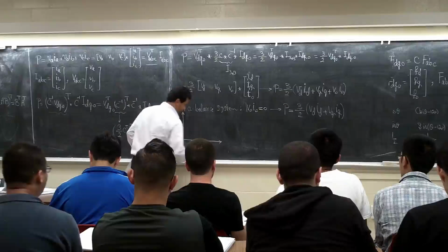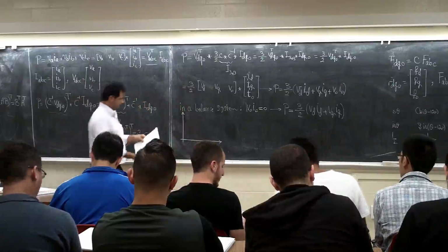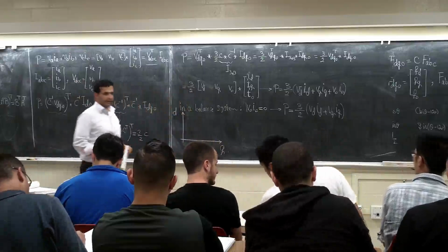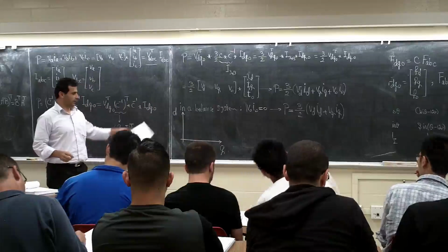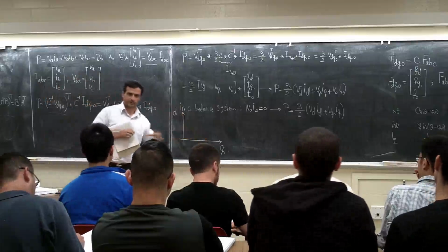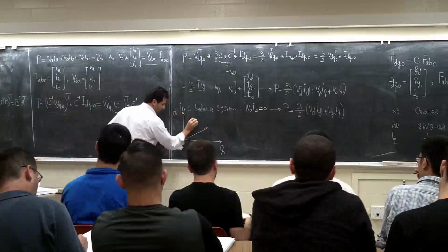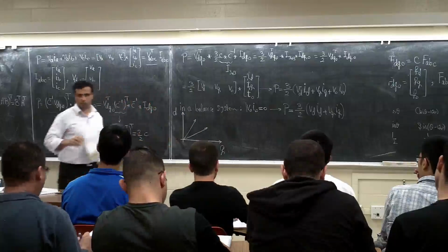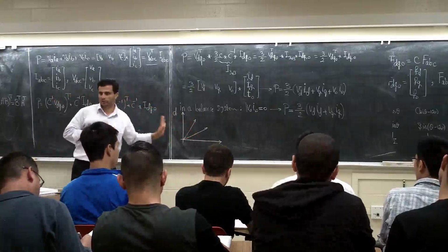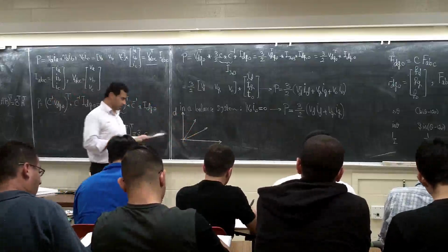Let's put this one here. How do we define these cases? This is my D-axis. This is my Q-axis. I need to calculate the reactive power. I put my D-axis, Q-axis from the frame I had here. Now I want to put my current and voltage vectors here. In general, it could be VAIA or VBIB or VCIC. Usually we go with VAIA first.